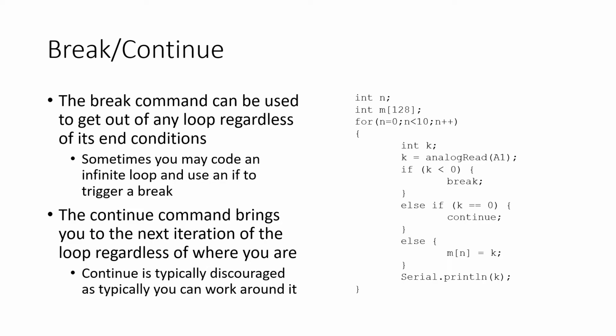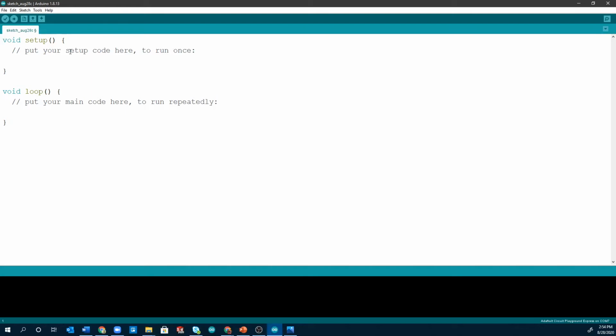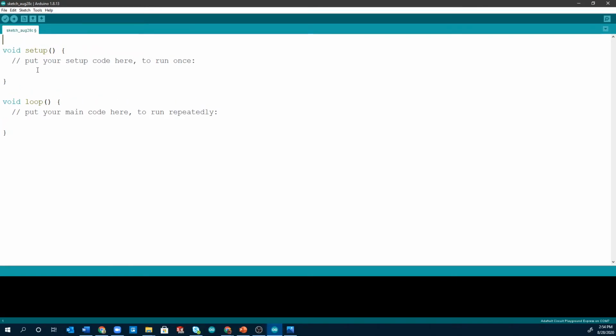So let's take an example here using our Arduino. For today's example, we're going to take a bunch of readings from a temperature sensor and we're going to average them together to determine the local value. To do this, we're going to start by defining our temperature sensor port. To do this, we're going to use #define, and the port, we're going to call it TS, and the port that we're on is A9.